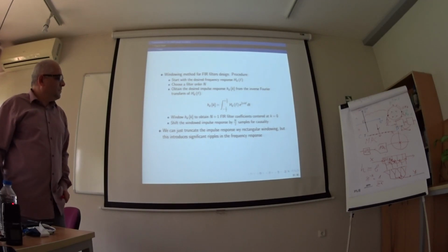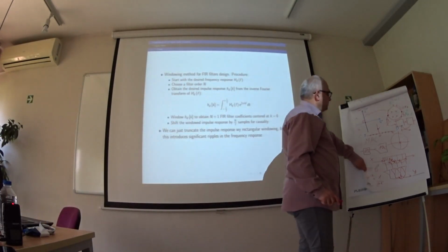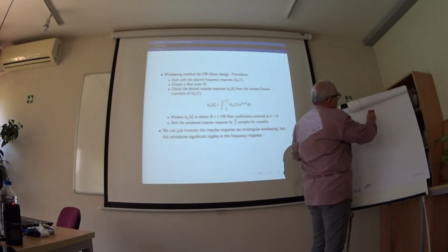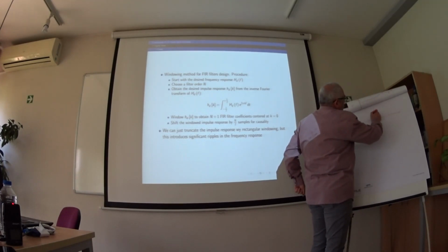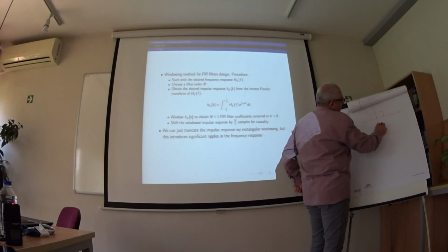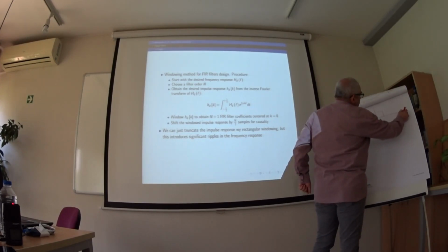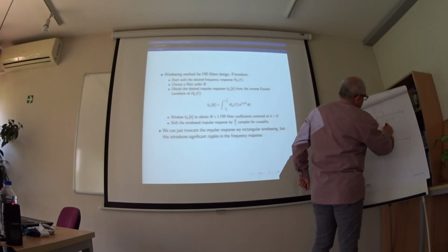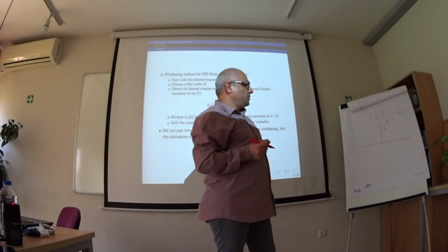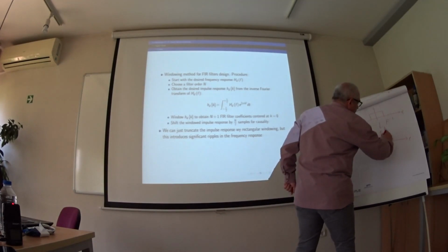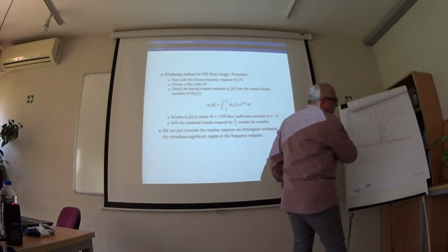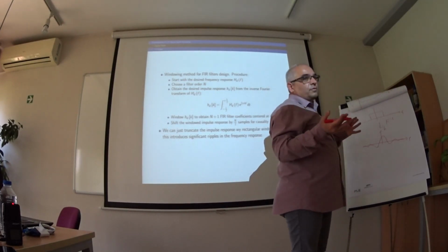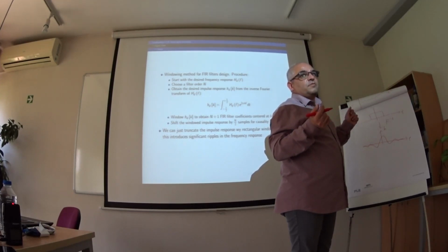the idea is, if we have an ideal filter with brick-wall frequency response, if I make the inverse Fourier transform in time domain, I will have the impulse response, but it will be sinc. How long? Infinity. I cannot make an infinite number of coefficients.